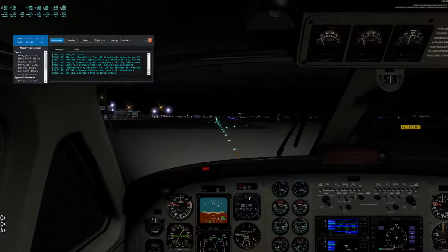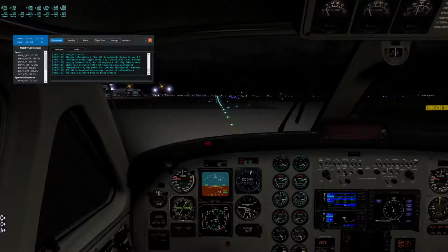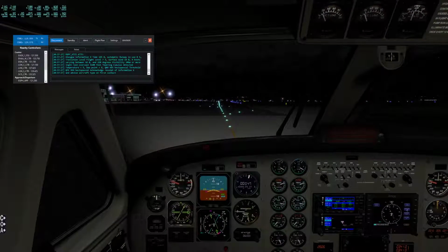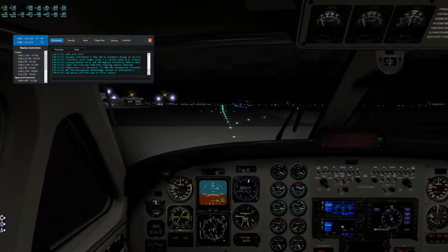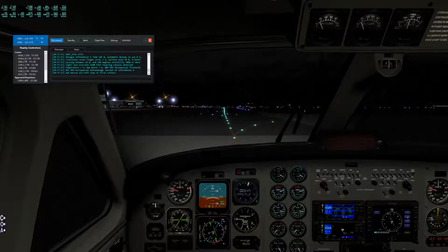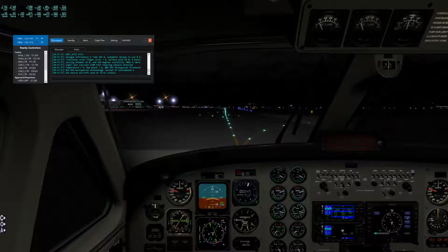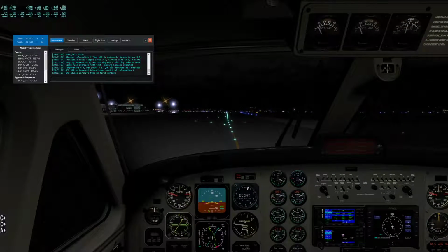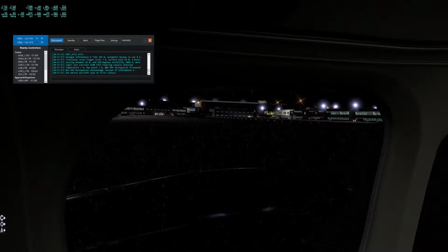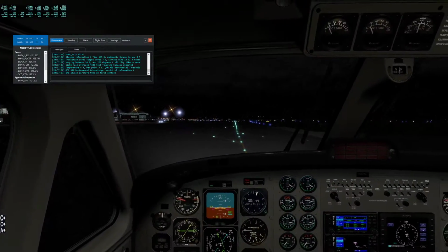Again, I should know that. I know that normally I rotate at just over 100 without flaps, but as you'll see during the takeoff, I kind of end up doing that anyway. I don't really gain anything from the flaps other than slightly slowing down the takeoff roll, although I suppose if I had to rotate earlier, at least there would have been a bit more lift.